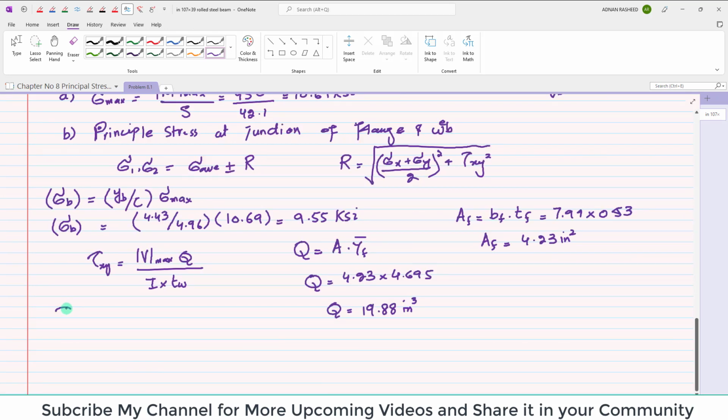So you can put the value. Clear? And this Q is equal to 19.88 divided by I, which is given as 209 inch 4, and thickness of web is 0.315. So if you calculate it, this shear stress will be equal to 13.58 KSI.